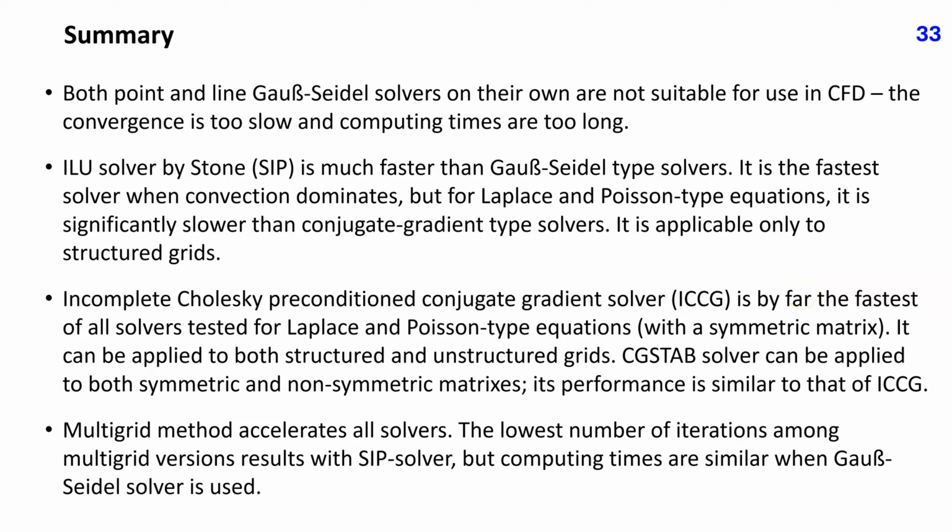Here is a summary of this lecture. Both point and line Gauss-Seidel solvers on their own are not suitable for use in CFD. The convergence is too slow and computing times are too long. The ILU solver by Stone, called SIP, is much faster than Gauss-Seidel type solvers.